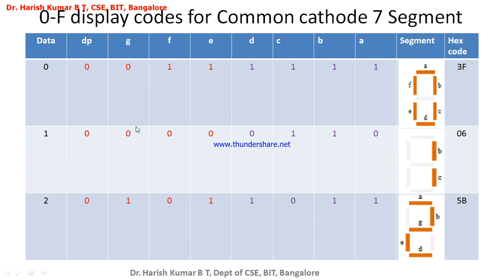Now when I write the hexadecimal equivalent of this binary number, I got 0 and 6. Now I have to apply the data 06 to the port pins of the microcontroller to which the common cathode LED segment is connected in order to get the digit 1 in the common cathode 7 segment display.